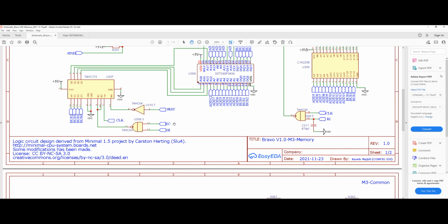So in this case, whenever you want to read something from the bus and put it in our bank register, we could bring the EC and HI signals both high. And when we bring both of those high, obviously the output of the NAND gate will be low. That's what we need to enable this register and read the data from the bus and save it into our register.